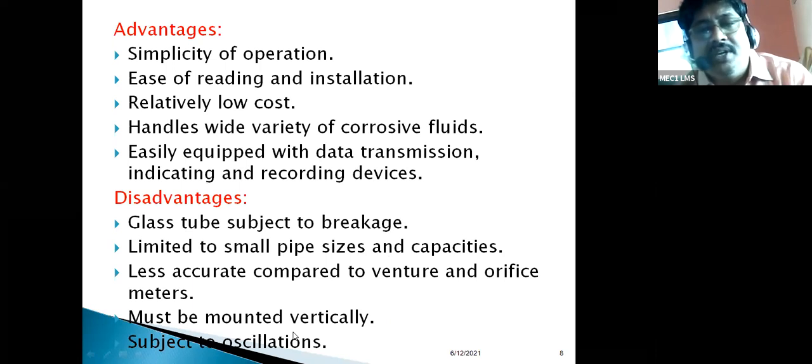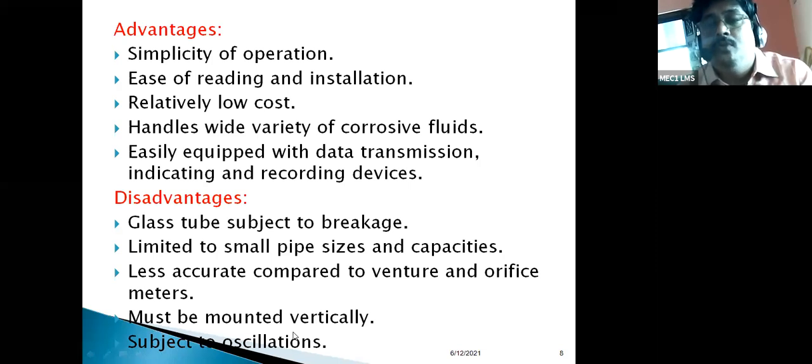It must be mounted vertically. This is very important. Actually, this meter we have to mount vertically. It is very, very important. Otherwise, if you mount it horizontally or inclined, it will not work. So that is the disadvantage: we have to mount it vertically, right?